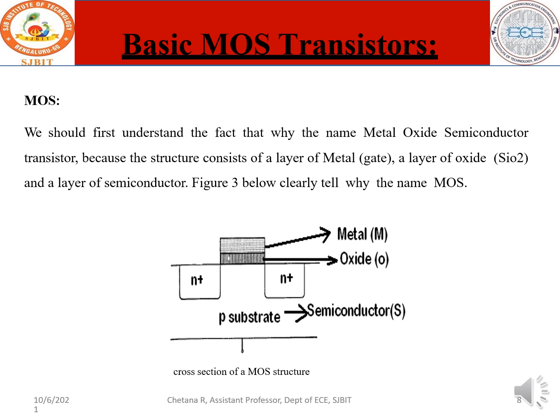So on this substrate, if you take it as P substrate, the counterpart here will be one more diagram which can be constructed using N substrate, and in place of N you would have P. So in place of P substrate you would have N type. And this P is nothing but again semiconductor. When this is exposed to air, the oxygen molecules will combine with this, and as a result they will form an oxide. And since it is silicon, silicon combined with oxide will give you SiO2.